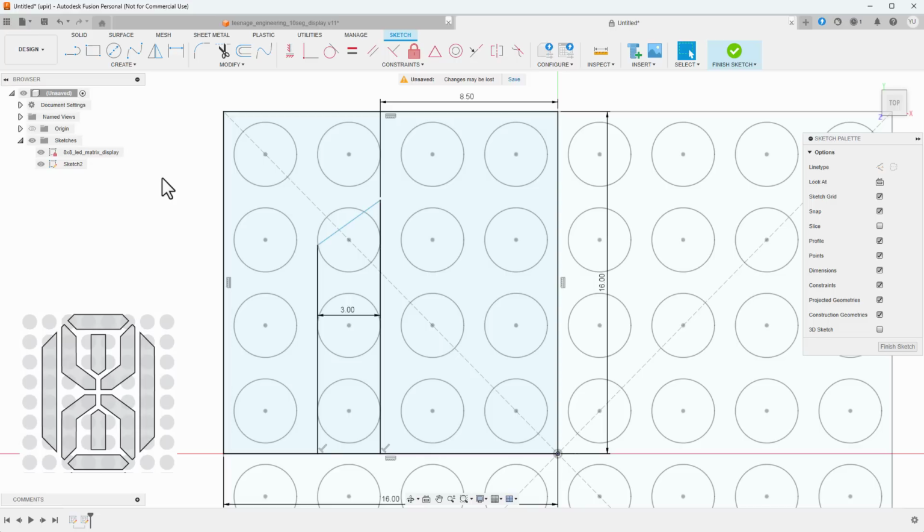Let's move on to the next segment, and again let's use the line tool to draw this segment. Let's start around here, then go down and closer to the center, but it shouldn't be touching the center, there should be a small gap, like so. Then going back, going up, and closing the segment with those two lines. Let's adjust the segment to look more refined, starting with the Sketch Dimensions tool and setting these dimensions to be again 3 millimeters. And also this dimension should be 3 millimeters.